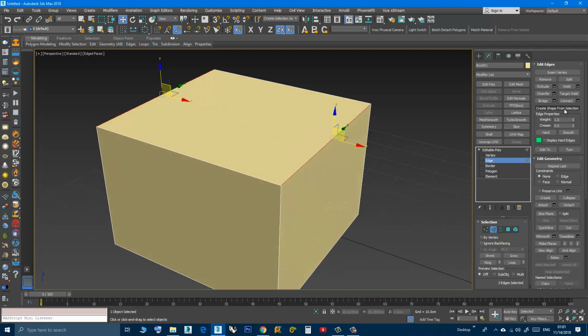Here, if I click this one, I have the chance to create a copy from these two edges as separate objects, as separate lines. I will choose linear. Well, in this case, smooth will not make any difference, but I will show you what I mean. I will choose 4 edges. I'll hold Control, so now I select 4 edges.